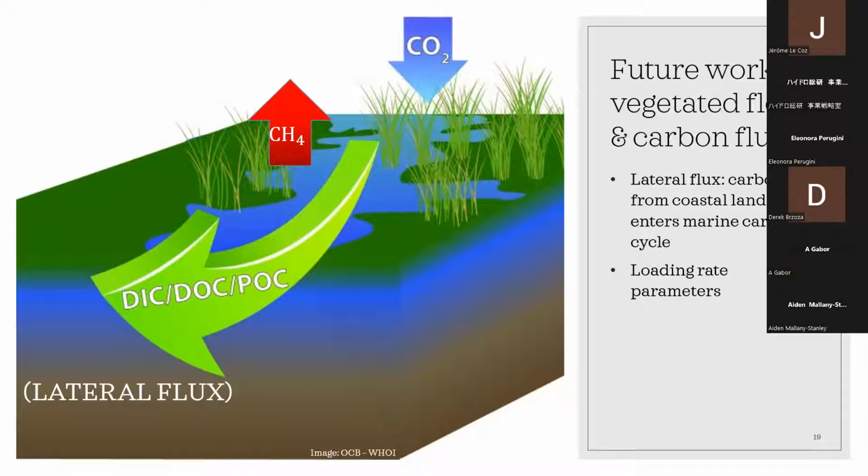So what we want to do is point a camera at the surface of the salt marsh after high tide while the water is draining through the marsh plants, and try and measure a discharge rate through that and measure velocities, and really see what we can do with the loading rates or the per concentration values for carbon that the Park Service and USGS have collected, and see if we can extrapolate that to a flux out of the system.